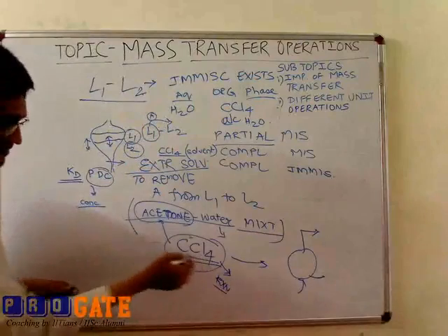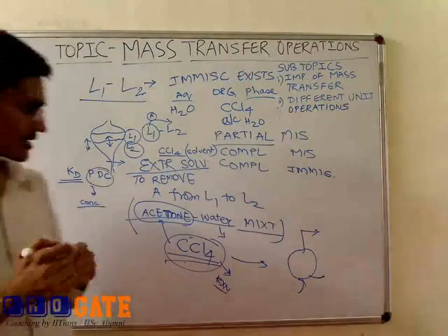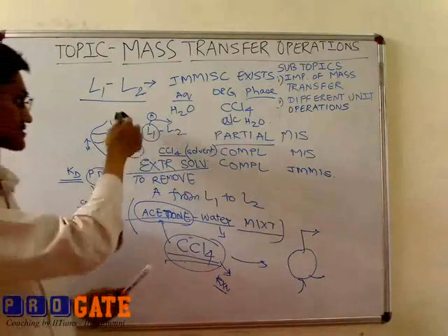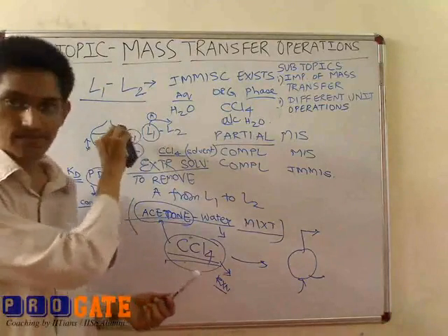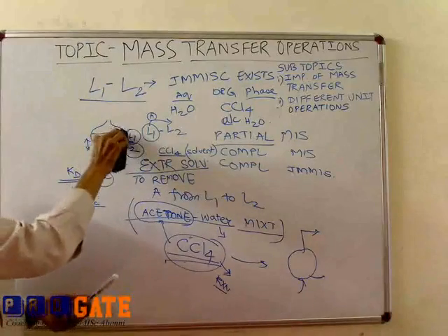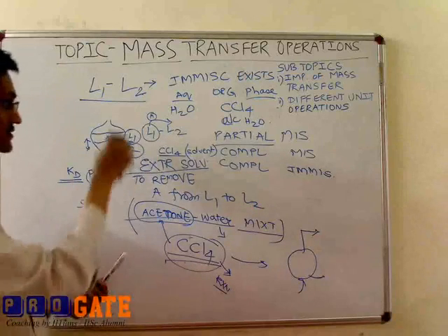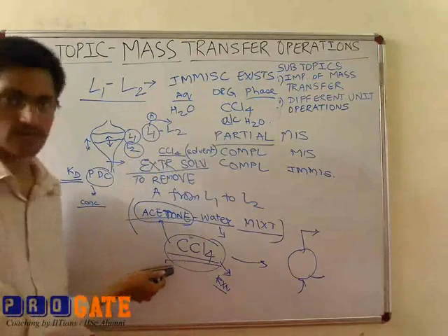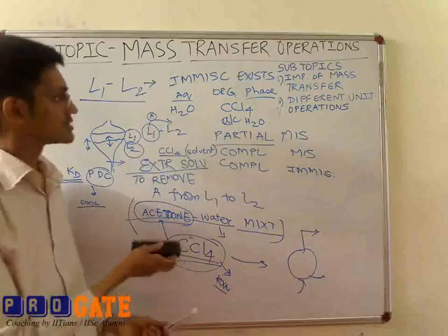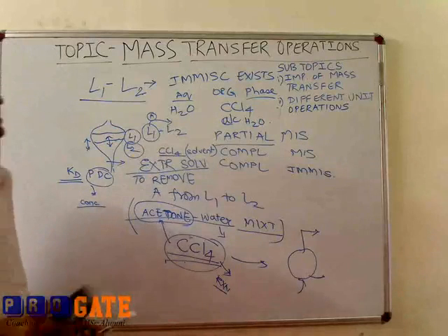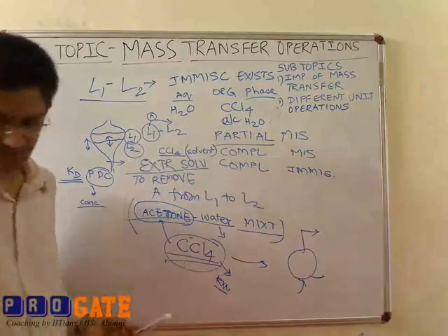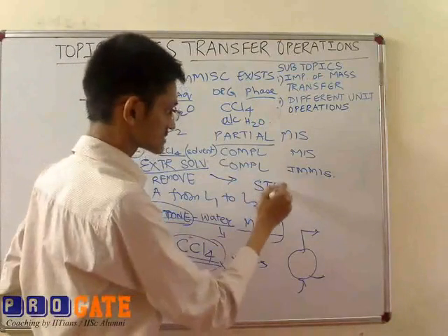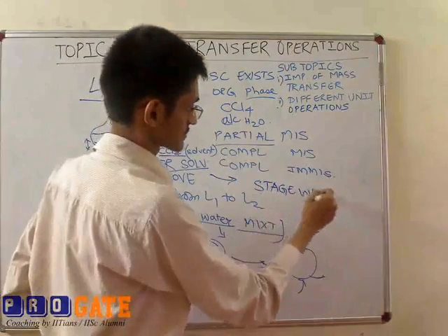It also involves different factors depending on the aim of the experiment. So basically what you do here is mix vigorously, so there is mass transfer involved, and then you allow it to separate, settling of the two phases, allowing it to reach equilibrium. So finally we get the concentrated solution of acetone in the organic phase. So this is basically what we do in the lab, and this is called stage-wise extraction.